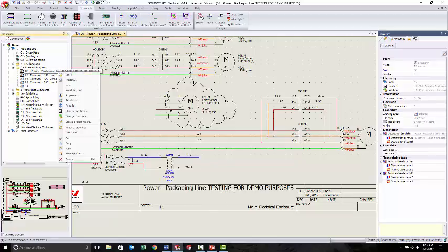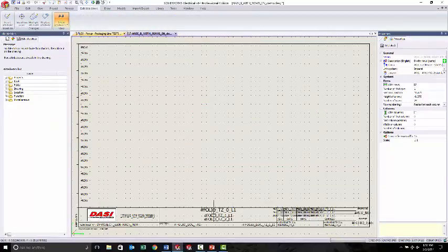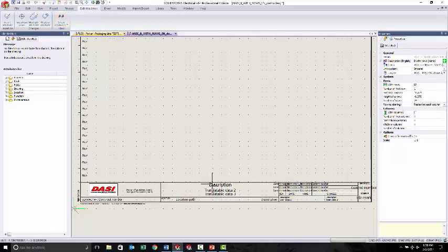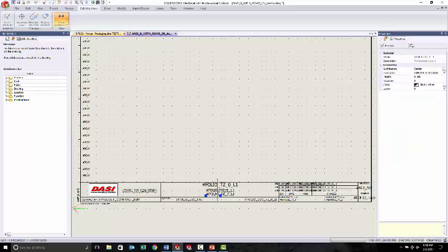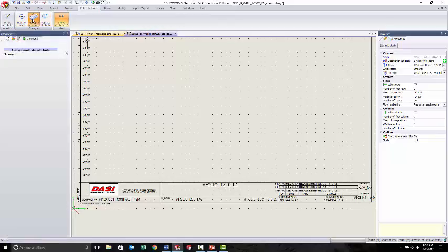If I open up the title block, and go into this. What I normally do here is, again, I don't know which one I'm looking at, so again, I'm going to show the attribute description. There it is, description. That is the one that I am working with. Great. So now that I know that, show the attribute. I'm going to get rid of these other two because I don't want them. All right. To create a multiple attribute, what it's going to do is give you that one attribute that you can make extra long and have it actually take up 2 lines of text. All right, so I've got 2 lines of text.